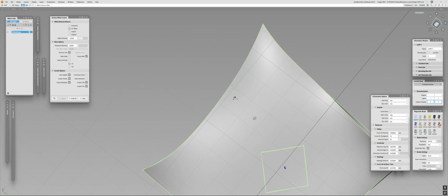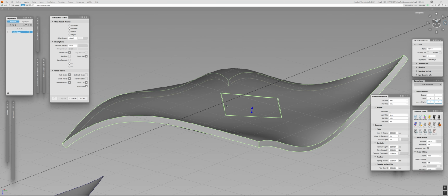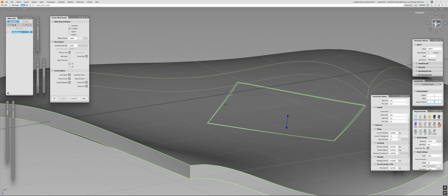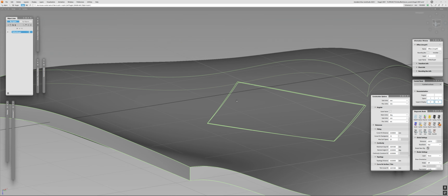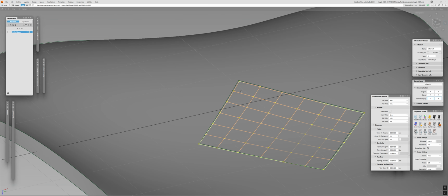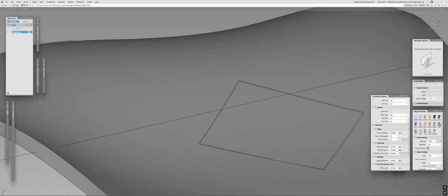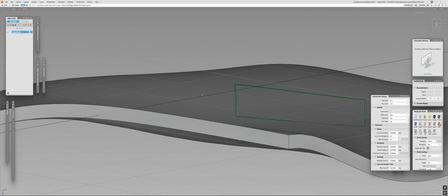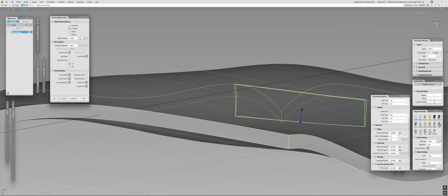So, okay, well, it looks accurate, but if you look closer, oh my God, what is going on? Here we have a gap, a significant one, as you're going to see. That means that when we work with the CV offset and you have a multi-surface construction, when one surface trims another one under different angles or something like that, chances are that the CV offset will not work. It works and gives you clean surfaces only when they are close to zero.